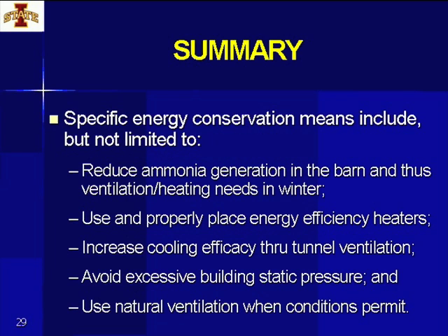A few specific energy conservation means include reducing ammonia generation in the barn and the ventilation and heating needs in wintertime, using and properly placing energy efficient heaters, increasing cooling efficacy through tunnel ventilation, avoiding excess building static pressure, which I cannot emphasize enough, and also using natural ventilation when conditions permit.